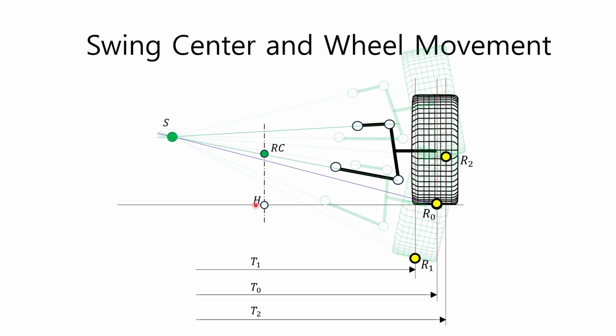In addition, since the suspension links have no force to support the sprung weight, the probability of the vehicle's bottom contacting the road increases even with relatively small lateral acceleration. Increasing roll stiffness to prevent excessive roll angles can lead to a deterioration in ride quality. Therefore, the roll center height of vehicles currently on the market is not on the ground and is determined by compromising to balance the overall vehicle performance, such as ride comfort, underbody clearance, and handling.